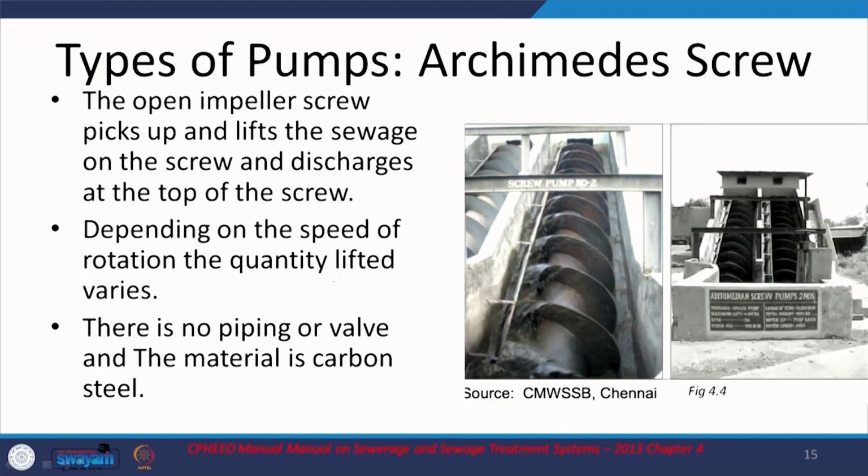The other one, as I mentioned, is the Archimedes screw pump. As you can see, as this Archimedes pump rotates from around this height, the water is being brought up to this height. So, depending on the speed or velocity of rotation, your water will be taken up to this particular head, and that is what you see in Archimedes screw pumps.